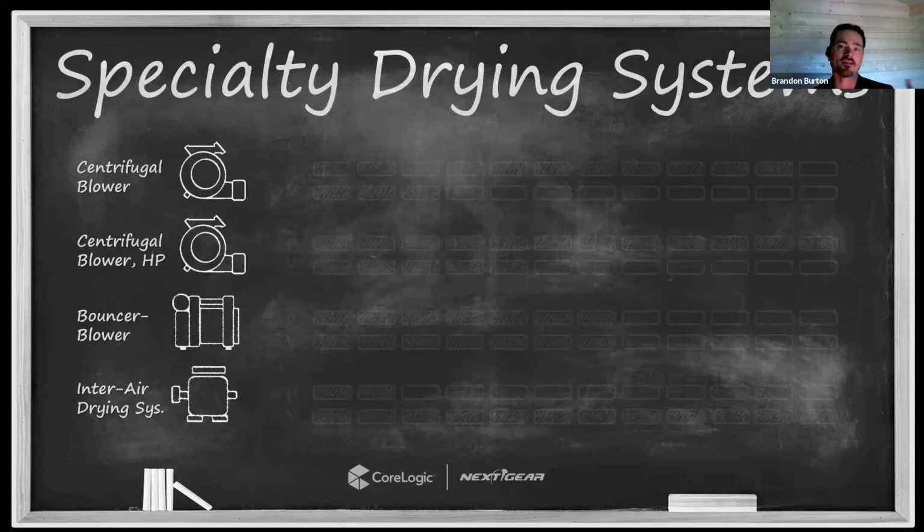Dehumidification will affect the interstitial cavity if I can install air movement that forces an exchange between the air in that cavity and where my dehumidifier exists. Whether I'm feeding the equipment directly with dehumidification, or I'm just forcing that air into the living space and then dehumidifying it with the rest of the air within that space. Understand as you install the system: is the air in that interstitial cavity air that I want to mix with the living space? We just talked about hazardous materials and concerns like that.